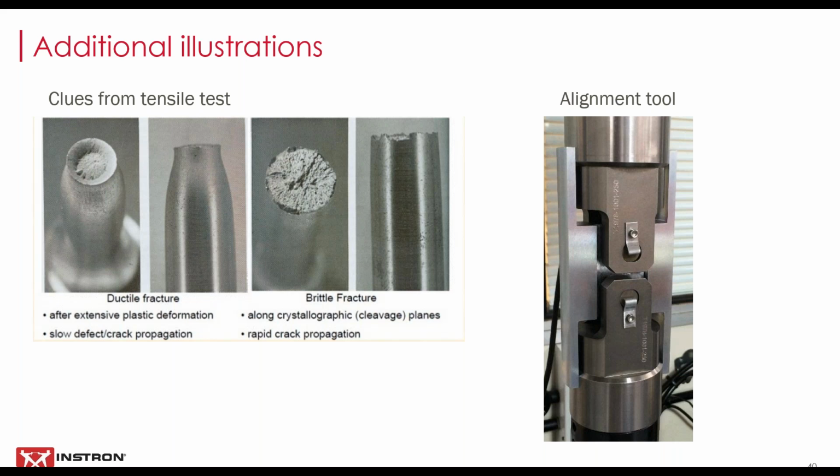By contrast, if you look at a brittle fracture, there's usually very little necking, very little reduction in cross-sectional area, and typically a very flat fracture surface or breakage across the specimen. Your stress strain plot will go up in a nice straight line and maybe curve over a little bit, but then a very abrupt failure.